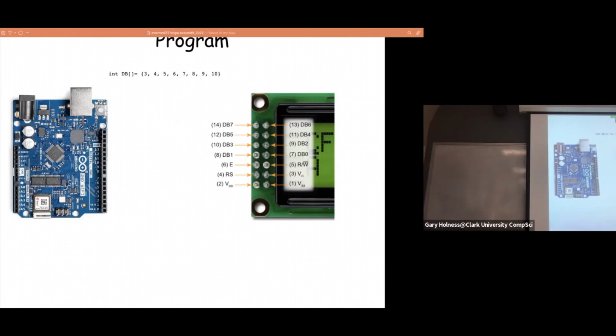And so when you wire, I recommend that you use the wiring in the example so that you can use the example code quite readily. You're mapping from a digital I/O line to a signal pin. And so here, the choice of DB is to mimic the DBs describing the data bus for the signal lines on the device.